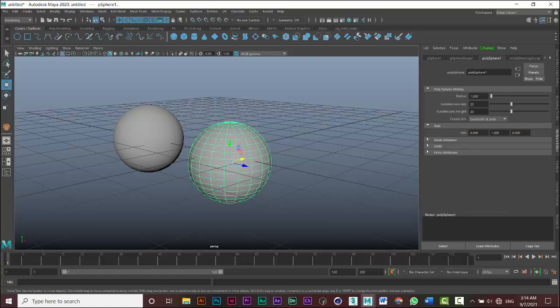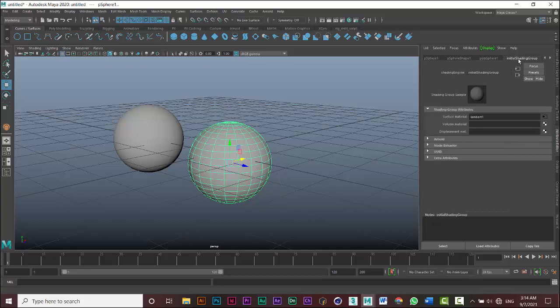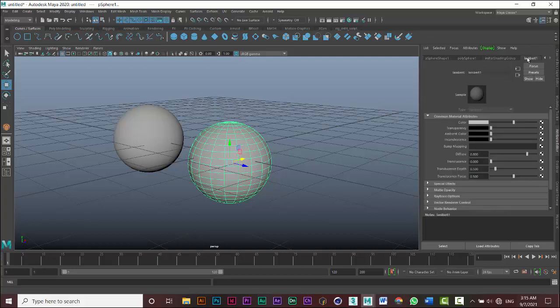So like I said, the attribute editor shows a whole lot more than the channel box, even the shading of the objects, initial shading. Now we'll get into shading when we talk about the materials. So first of all, the rule of thumb: don't change this color yet. Don't change this. This is the initial shading group. If you change this color, every object you create here will attain that new color you assigned here. So please don't change this.